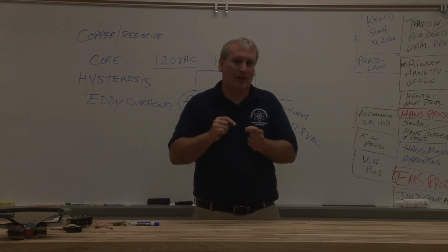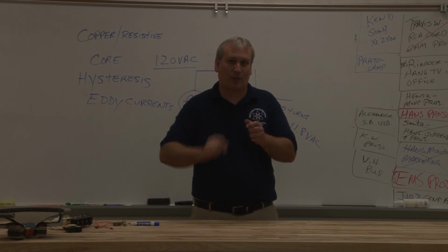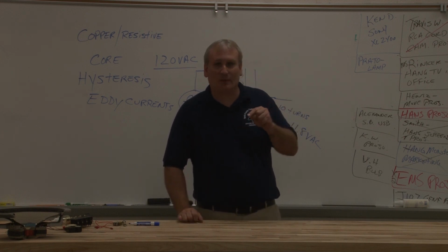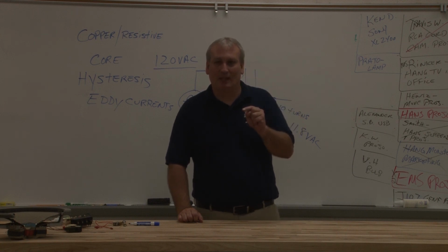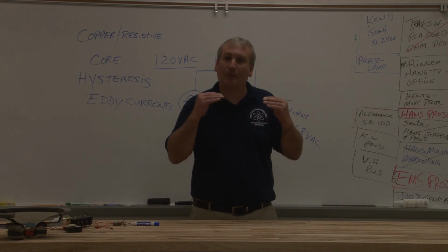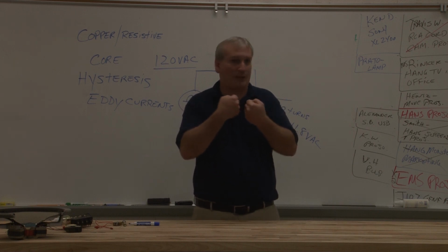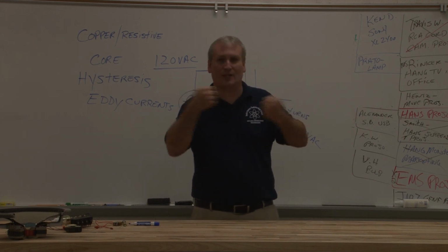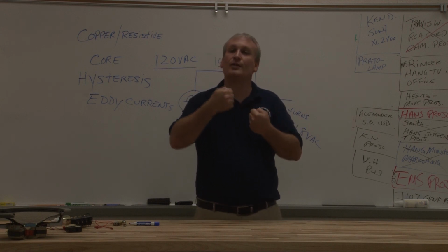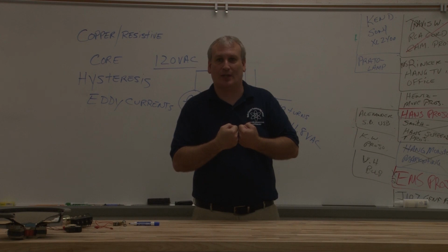Well, again, we have some retained magnetism because of hysteresis. We also have these currents in the transformer that are building up and collapsing and building up and collapsing, and these magnetic fields that are building up and collapsing. And then voltage quickly changes, and we get another build up and collapse. So we end up with some of these eddy currents and these magnetic fields and these voltages that are constantly changing direction and bumping heads and causing some more cancellation. That's called an eddy current loss.